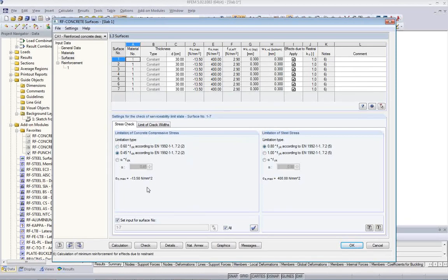Regarding the code, there are certain settings that limit the compressive stress, and you can just choose them. Everything is set up by default, so in general you wouldn't have to change anything. Also, stresses have to be limited, for example, typically to 80% of the yield stress of the material. If you want to, you can set those settings individually for each surface.